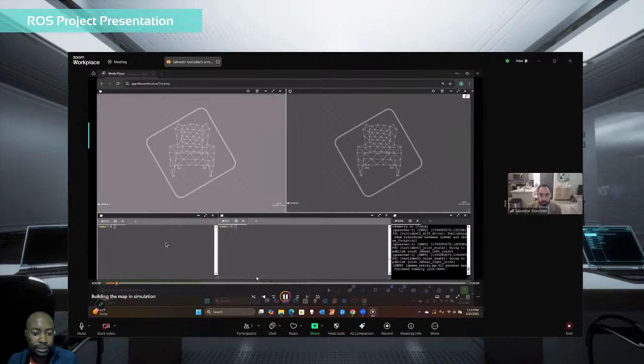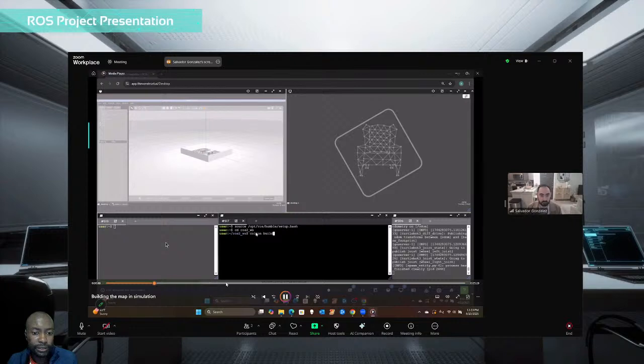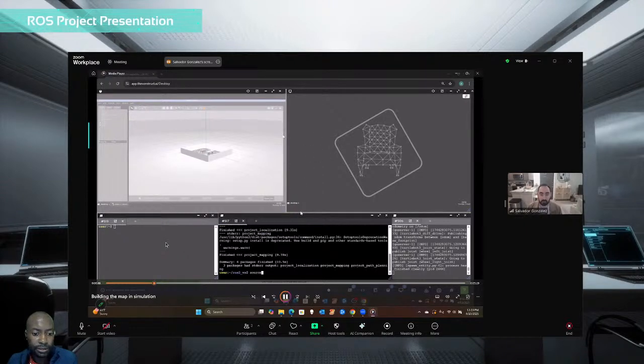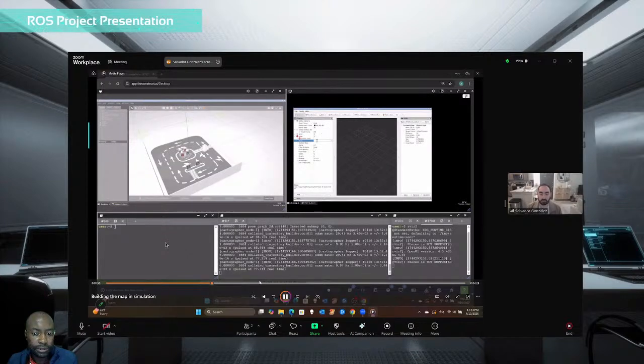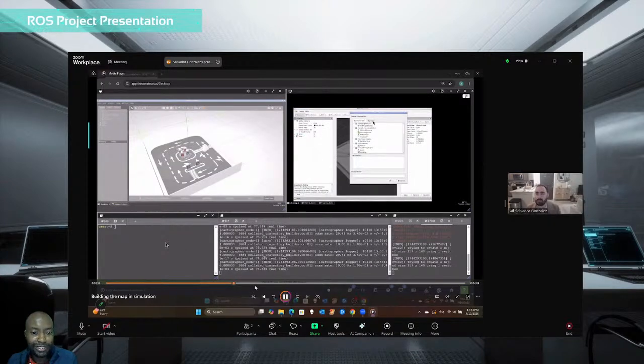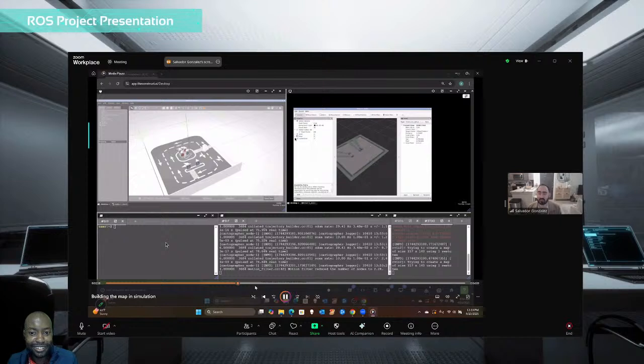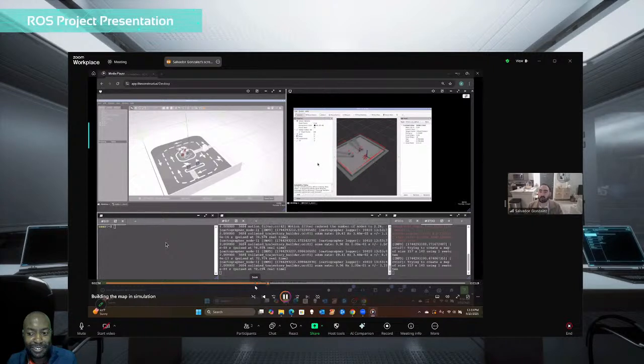So we can see here, things are just starting. Here I set up the RViz configuration. I show how to do that. I show the importance of setting certain quality of service things. Oh, this was actually really helpful, dealing with AMCL and the quality of service, because in the ROS basics, you guys introduced reliability, and I said, okay, I think I get that. And then I had a whole problem with getting Spot Recorder to work because AMCL was not updating.